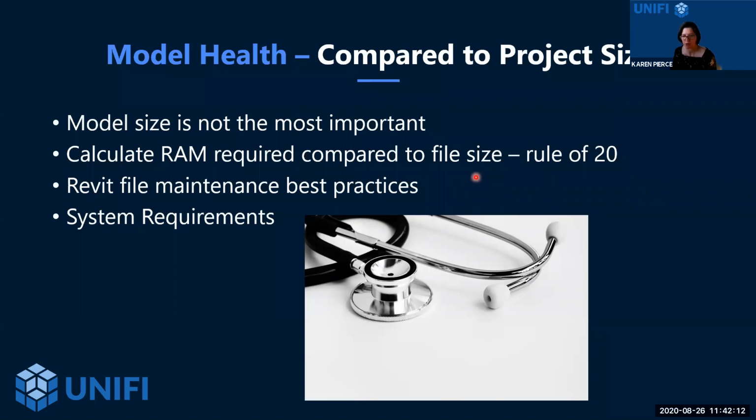And while that doesn't quite affect the rule of 20, it definitely does take effect. So the bigger your projects are going to get, the more RAM you really will want to have. And keep in mind, Revit's probably not the only thing on your machine using RAM. You likely have your internal chat going through there. That uses RAM. Outlook uses RAM. So there's a lot of programs out there that will be using that RAM in addition to Revit.